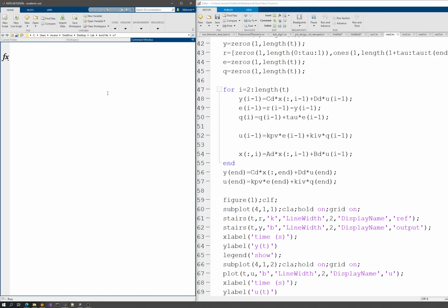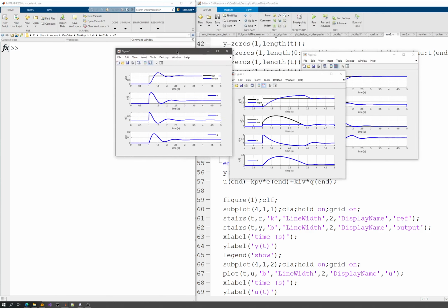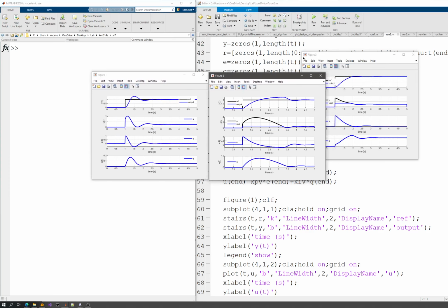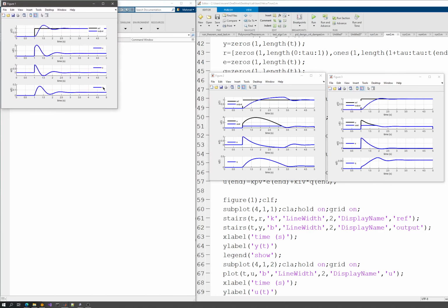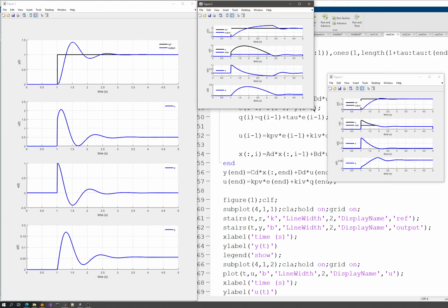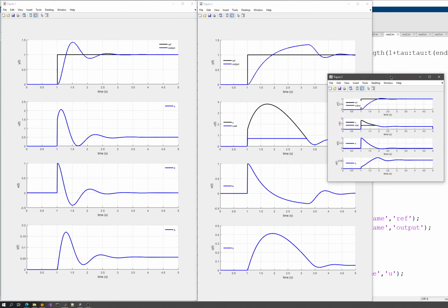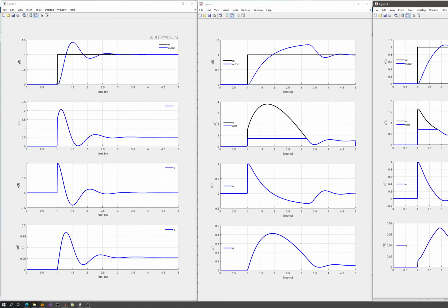They should give me 3 different figures, which will correspond to the actual, non-saturated version of my signals, the saturated version, and the windup version and the anti-windup version here. Now let's adjust them so that we have bigger signals here, and I will be able to compare them at a glance. I can see now and observe also that the behavior of the system didn't change very much, because my restriction did not allow the overshoot that much, because I had a restriction on the control signal.